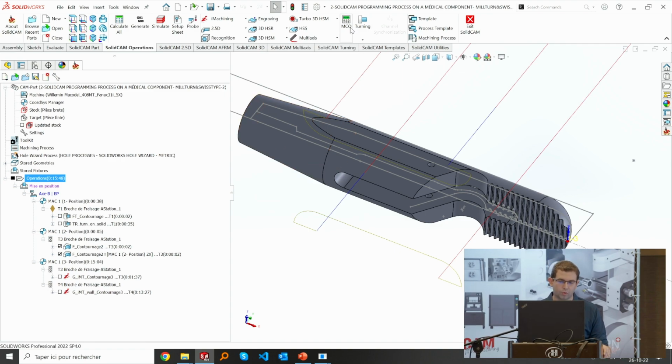So in SolidCAM, we have what we call the MCO that allows you to program external equipment of your machine. But the transfer is something recurrent. It's always the same. I come with the rotating unit, I clamp the part, I cut off, then I move back, and I switch to vertical position.